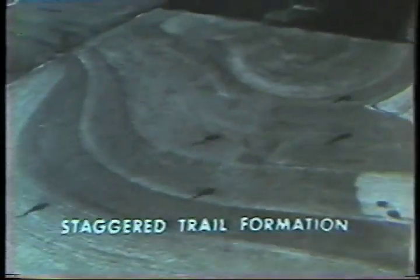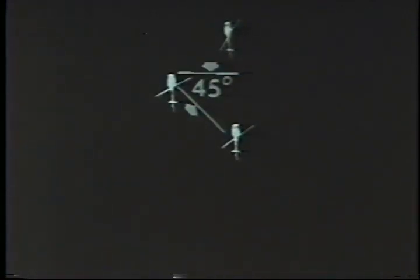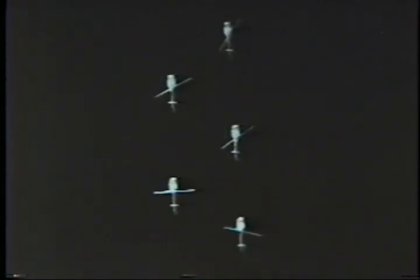There are 2 types of staggered trail formations, staggered trail left and staggered trail right. In the staggered trail left, number 2 aircraft is 45 degrees astern and to the left of the lead aircraft. Number 3 is directly behind the lead, 45 degrees astern and to the right of number 2, with number 4 and number 5 alternating left and right. Each aircraft maintains a 2 rotor disc separation between helicopters and a 3-foot vertical step-up on their respective aircraft.